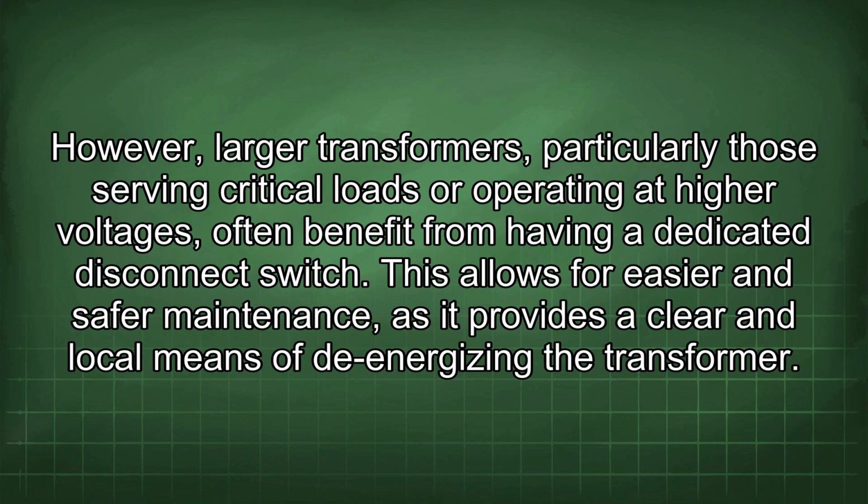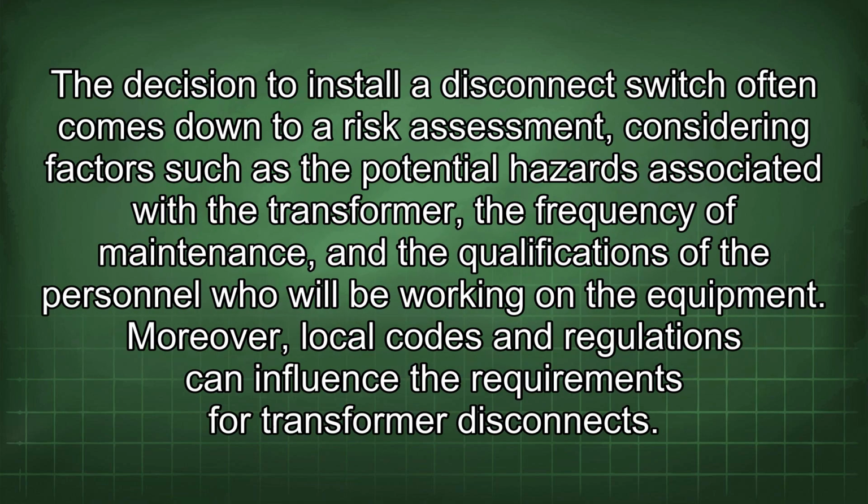However, larger transformers, particularly those serving critical loads or operating at higher voltages, often benefit from having a dedicated disconnect switch. This allows for easier and safer maintenance as it provides a clear and local means of de-energizing the transformer. The decision to install a disconnect switch often comes down to a risk assessment, considering factors such as the potential hazards associated with the transformer, the frequency of maintenance, and the qualifications of the personnel who will be working on the equipment.